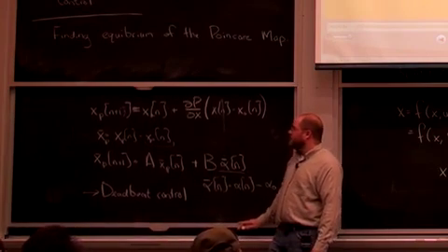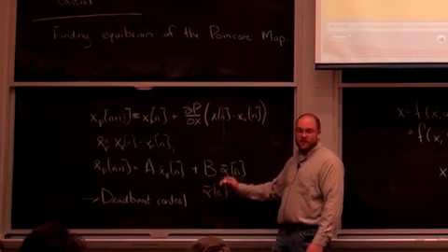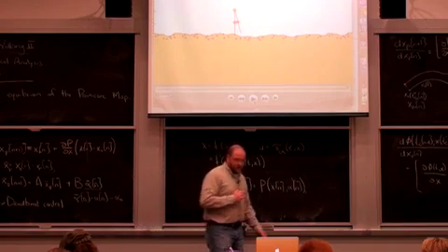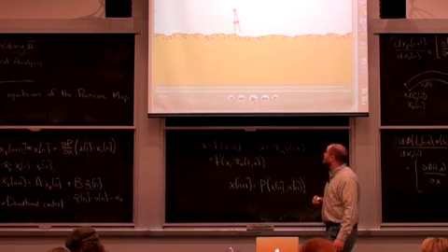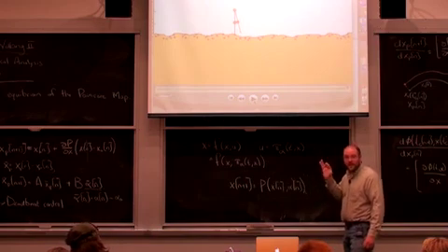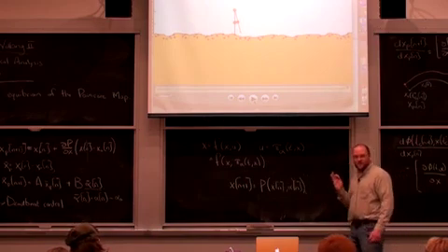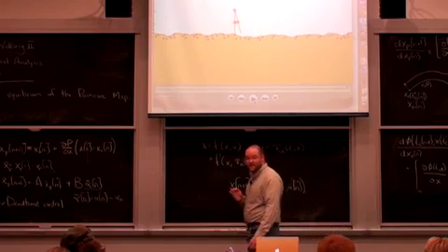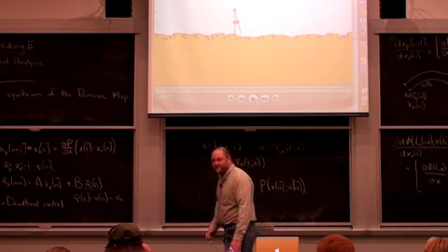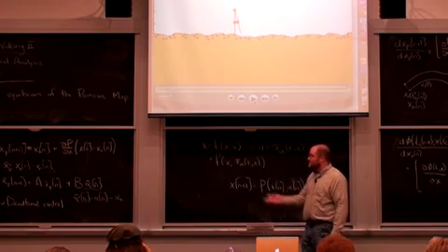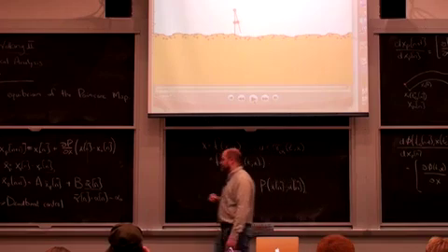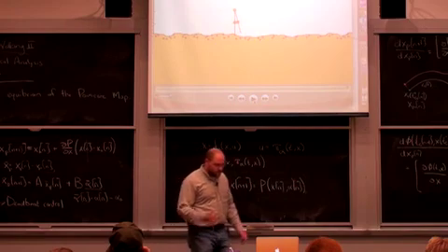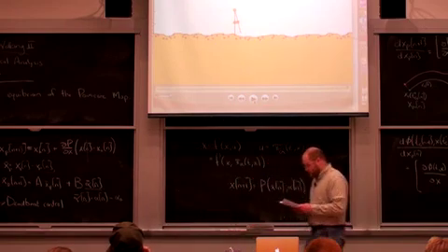We'll see in the running bit some running models where you can do deadbeat control. The compass gait, if you had the right parameterization, you could do deadbeat control. John and I were debating this last night. I don't think that the PD controller is probably going to be enough to give you deadbeat control, because it won't simultaneously take out your energy and get your foot in the right place. But it's possible we could actually do the analysis and answer that question. Thinking about these things as discrete time control problems is pretty beautiful.